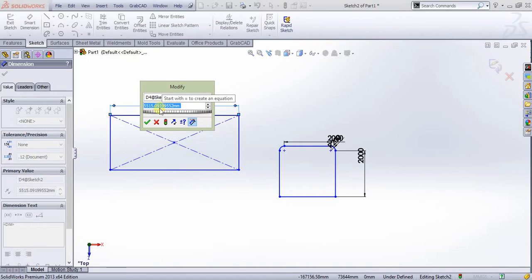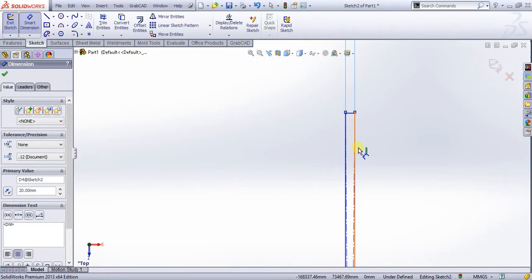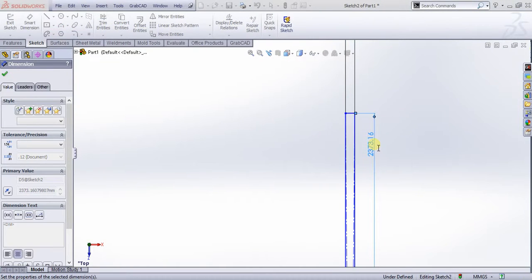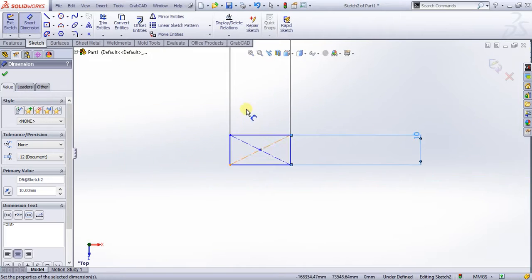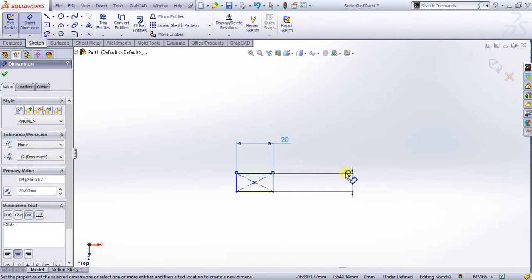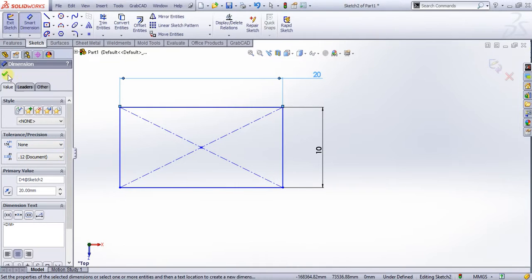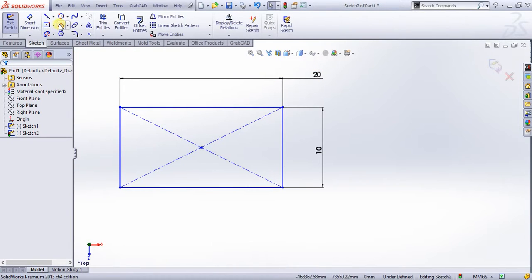You can set the length of the rectangle by entering the value here. Suppose I give it 20 mm. Okay, that's it. It gives 20 mm to the length and 10 mm for the breadth. That is converted to this, and we can drag it by clicking on it. The dimension can be set near the geometry, so we can get the required dimensions and important knowledge about the structure. We can use it for the circle as well.